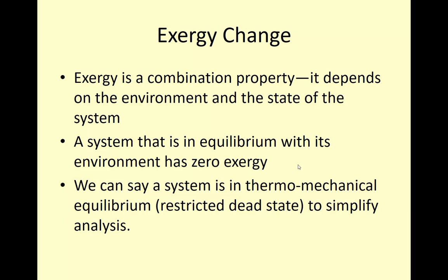And we can say that a system is in thermomechanical equilibrium. To simplify the analysis, this is also called a restricted dead state. So what we're looking at in thermomechanical equilibrium is that the temperature and pressure of the system are in equilibrium. We may be ignoring any kinetic or potential energy effects. We may also be ignoring any chemical reactions that are ongoing or any mixing that is occurring between the system and the environment. So thermomechanical equilibrium is sufficient for the analysis that we do within this class if we just look at the temperature and the pressure being in equilibrium with its environment.